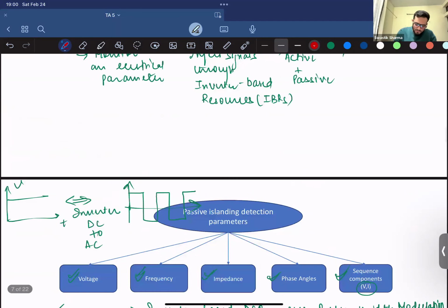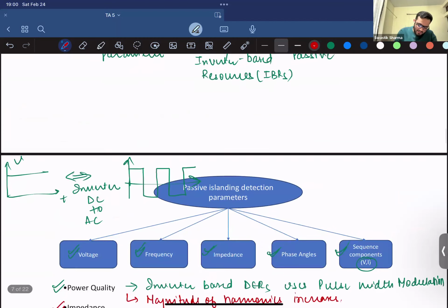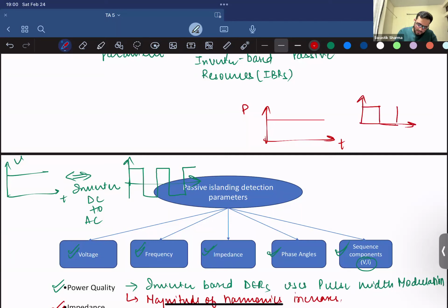So what someone did was they had DC. So let's say you had power. I'm not talking about DC power or AC. It's just power, and it's constant for the whole time. What you want to do is reduce this power to a certain level. So what someone did was they started switching it off, then on, then off. So under one cycle, the average was lesser, 50% lesser if you switch at 50% spacing, 50% less than the original. So that's where the concept of modulation using switches came into the picture, right?